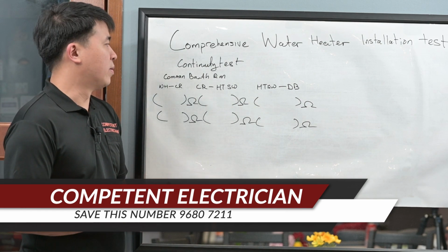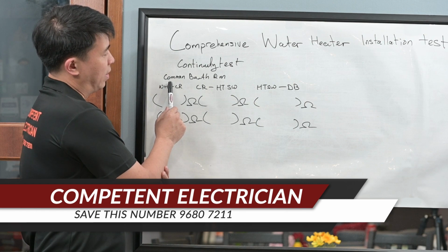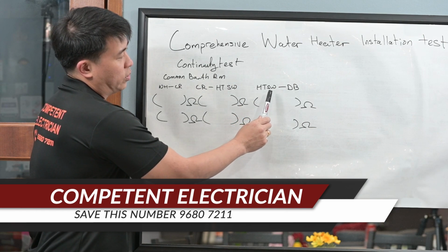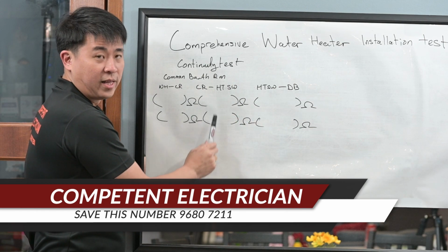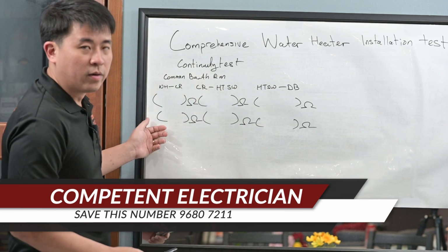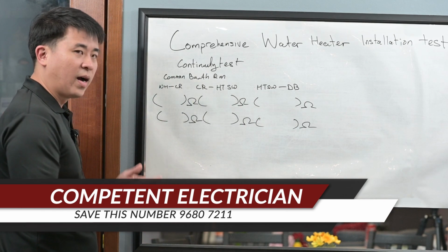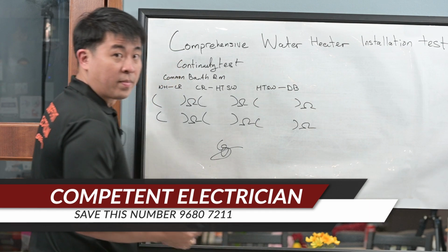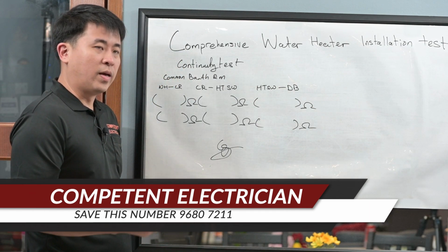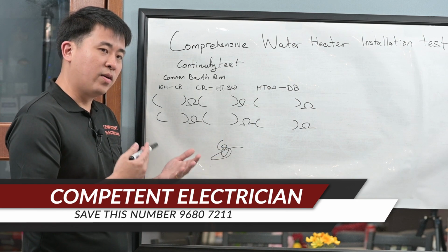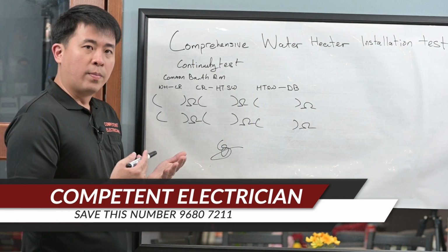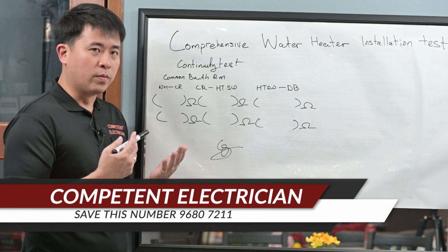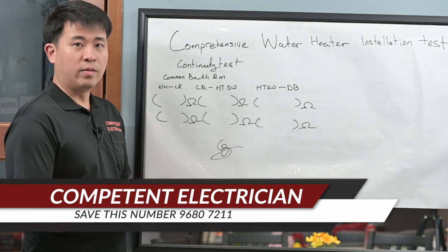The test comes with a simple report of the continuity test, like the common bathroom, water heater to ceiling rose, ceiling rose to heater switch, heater switch to distribution box, and the quantity tested. All the numbers will be recorded by my technician, and I as a LEW will authorize and sign on the document itself. Okay, and this document also tells you that all the items have been manually and specifically measured and tested. Please do this to protect yourself, and share this video if you think that somebody will need this information. Thank you and goodbye.